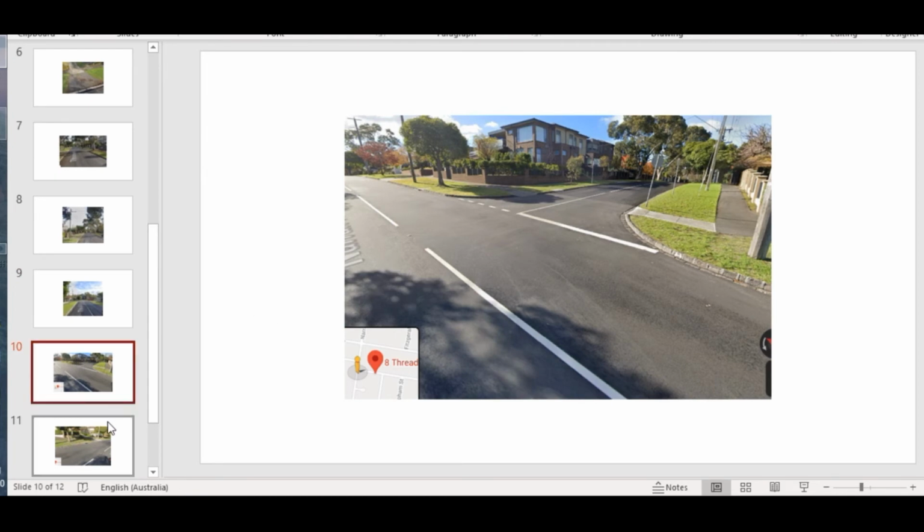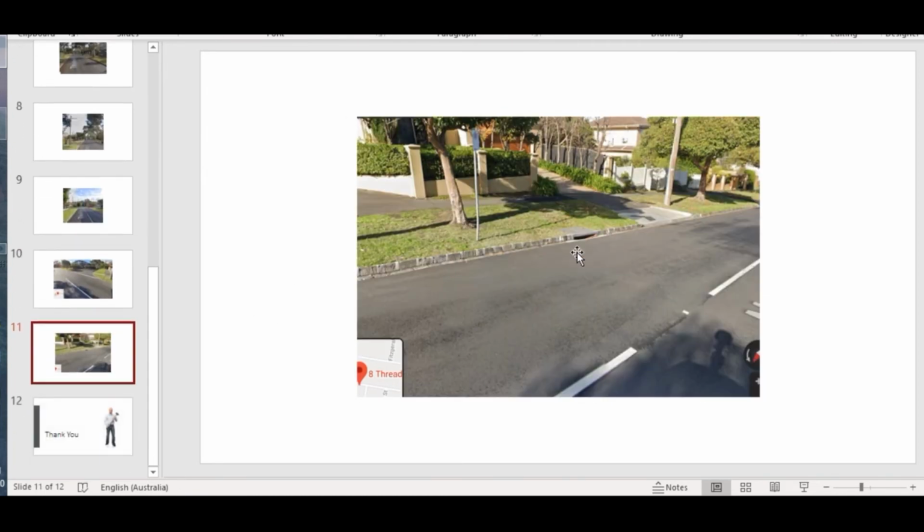Sometimes, as you can see here, an inlet lintel is being proposed. It might have a certain discharge as well as time of concentration. It then again takes a flow from the property into the kerb gutter, and from the kerb gutter there is overflow into the lintel. So there can be a roof flow: the rainfall falls in, so there will be a roof flow from the property that flows into the downpipe.